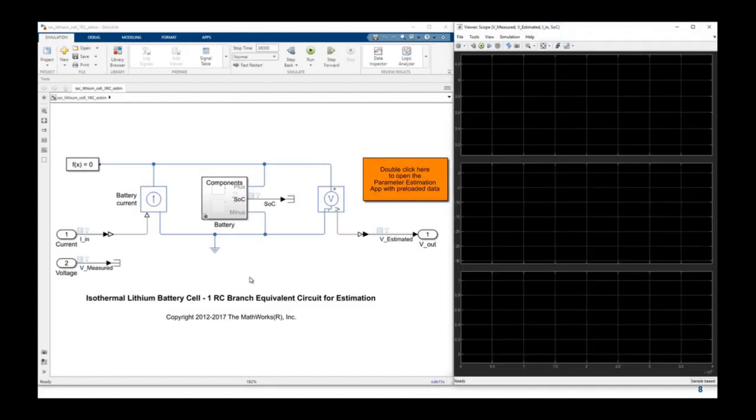I have seen in the previous poll that some of you know Simscape, but not a lot. So here I will provide you some more information about Simscape, because that's what we are using there. First, you can see that on the left-hand side, we have some input signals that are coming from Simulink. In Simulink, you always have an arrowhead that will indicate the direction of the signal. In Simscape, for a physical signal, you don't have any arrow. It's because within the physical domain, which can be electrical, mechanical, fluid, thermal, or whatever, the energy flux can always flow in both directions. So that's why there is no arrowhead.